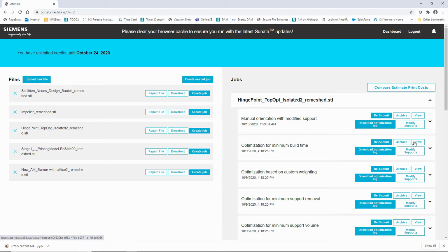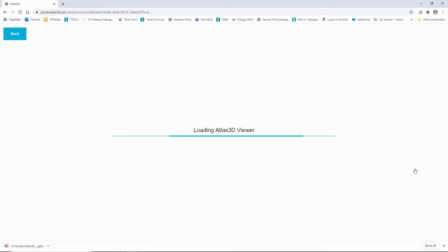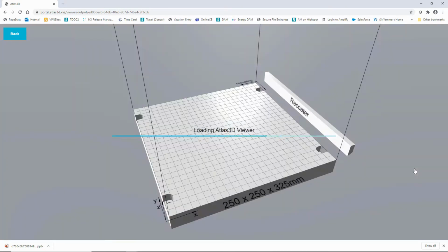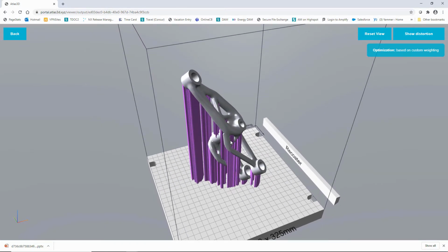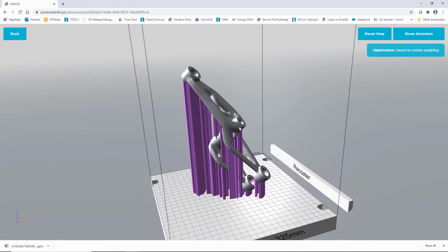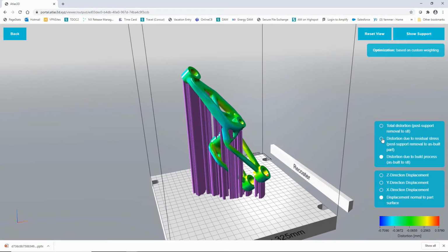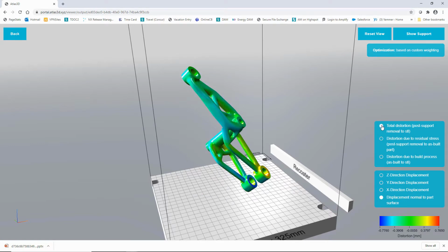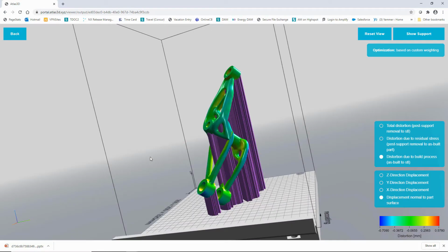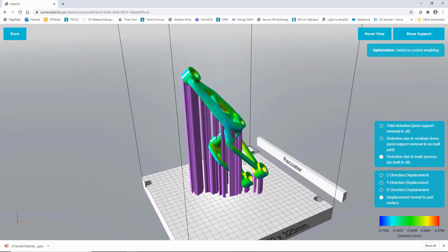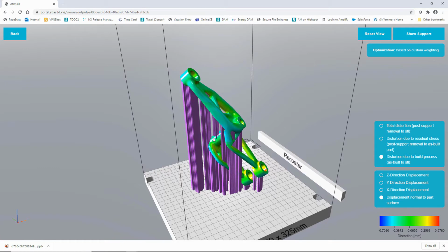Now, once you have the part you want to print, it makes sense to optimize the printing of that part, not as in topology optimization, but as in optimizing the actual production. So for example, Siemens has software for optimizing the orientation of the part in the build tray. This helps minimize distortion, minimize material usage, etc., so that your production is optimal and your part will print with quality the first time. Now, this particular system, called the AM Build Optimizer, is cloud-based and uses parallel processing, running over 100 different orientations in parallel to find the optimal orientation for your part in the build according to some weighted inputs that you give the system.